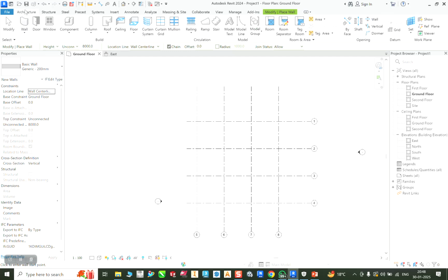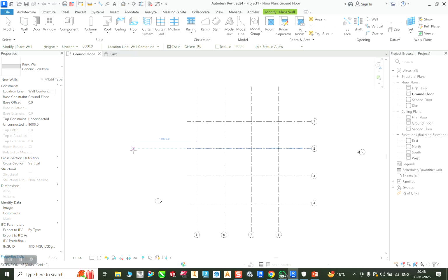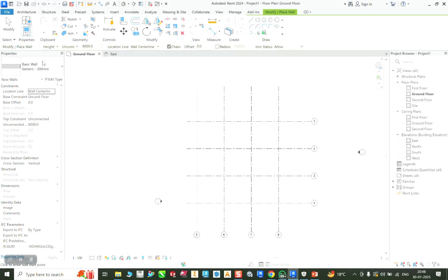Simply we have to click on that W. If you go ahead, WA. Can you see here with that parameter? Everything you will see the shortcut in that bracket. That WA is there. Whenever you want to type this, like I'm going to escape it and type WA, automatically that basic wall generation is going to come. So everywhere it is mentioned, but I'll tell you also. Okay, so up to here the levels and the elevations are clear.